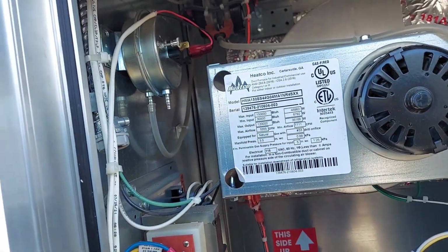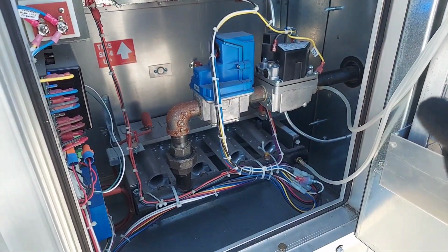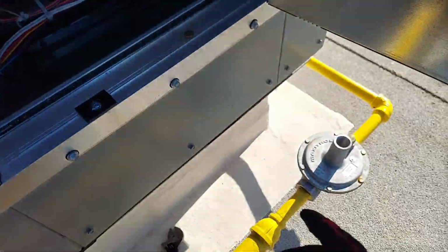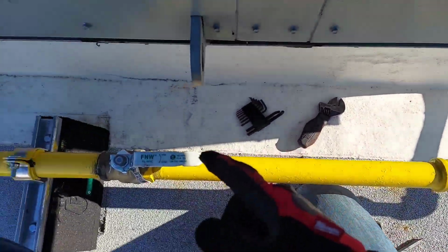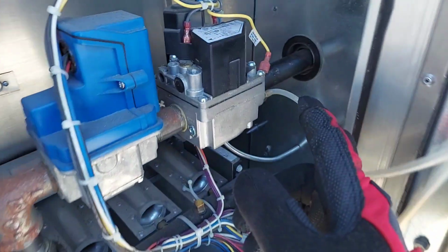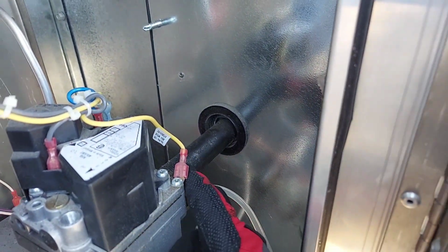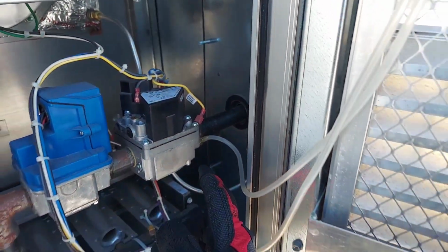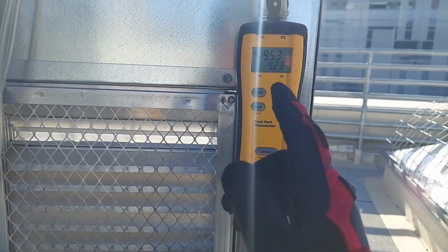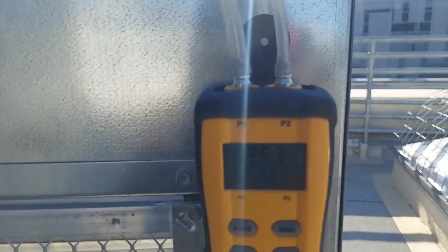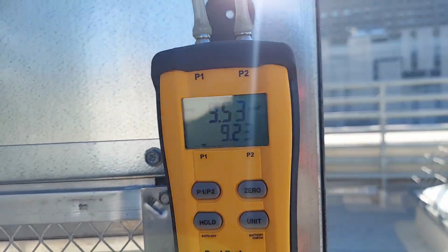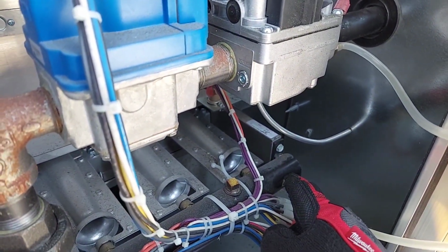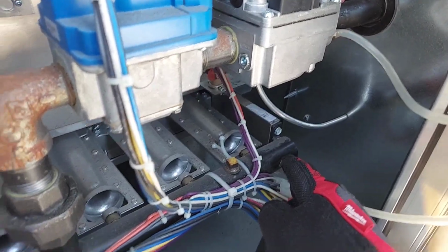As you can see, this is a commercial heating furnace. It's a brand new startup. Especially in the commercial world, if you're doing a startup, you're going to want to make sure that you have the proper incoming gas pressure. Right, incoming. That's the incoming side. You can see I'm tapped in with one of my pressure sensors from my manometer. I got 2 ports in here. It's a 2-port device. And the other one is on my burner, the burner header pipe.